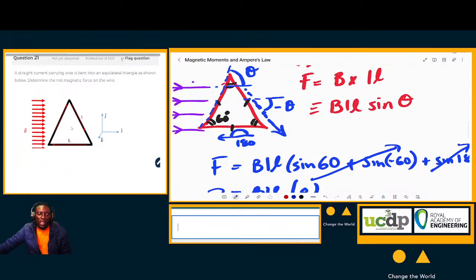But take note, this is generally force. We're looking at general force, but we can still have torque, because the forces are on one plane. Which rule did we say we use? The left-hand rule. So if we consider our left-hand rule, with the field by the first finger and the current through the second finger, you've got a field to your right, current is basically upwards, then the force will be into the plane.